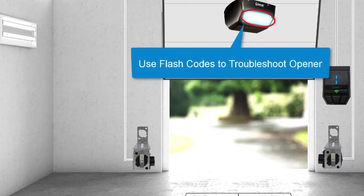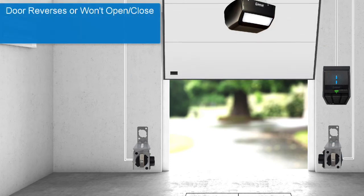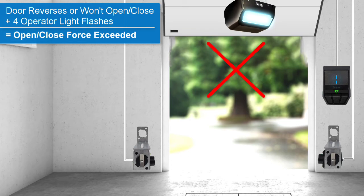These light flashes, or flash codes, are a helpful troubleshooting tool to determine the condition, cause, and solution to your door operation problems. If you notice your garage door reverses during operation, or won't open or close at all, followed by 4 operator light flashes, the operator's open or close force was exceeded.